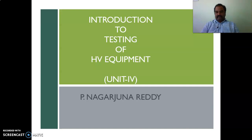In the last lecture, we have seen the different techniques for measurement of high currents. We have seen the Hall generators for measurement of high DC currents, current transformers with electro-optical fibers for measurement of high power frequency AC currents. We have come across magnetic measurements like Rogowski's coil, magnetic links, resistive shunts for the measurement of impulse currents. So that will end unit number 3.